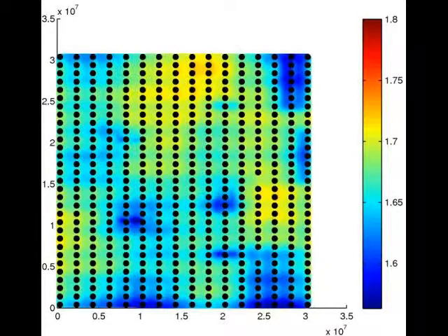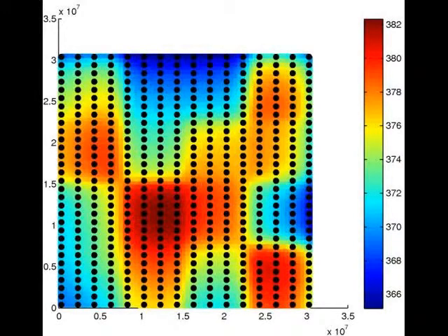An example static IR drop map for the IBM PG3 benchmark is shown here. As you can see, the voltages are within the design constraints. The equivalent temperature map for the IBM PG3 benchmark is shown here. As you can see, in certain areas of the IC there are large temperatures, which will exaggerate the electromigration constraints and make it hard to meet the voltage constraints.